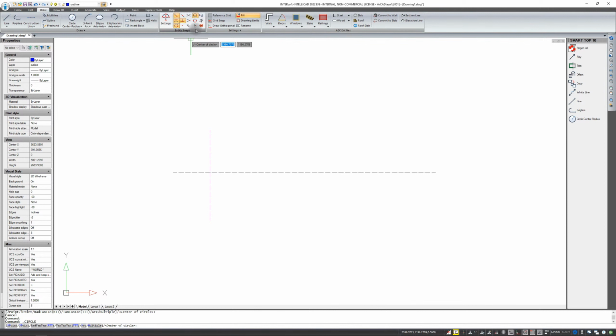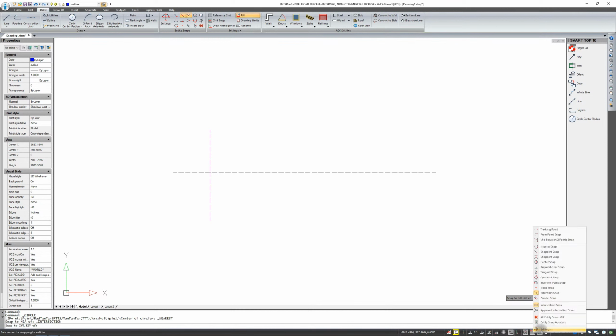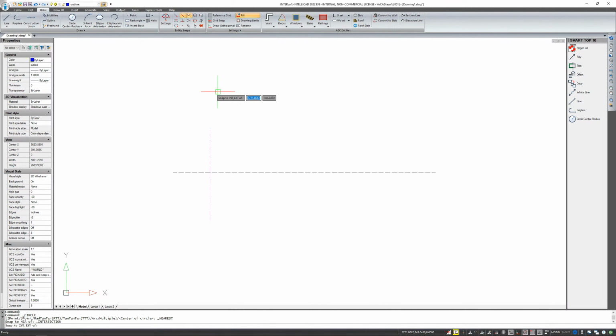You can turn all these elements on and off so that the program finds them. These options are both on the ribbon, in the draw part, entity snaps, and you can also set them at the bottom of the status bar, in the entity snap settings. And of course, you can also find the snap points under the right mouse button. The snap points have two states.